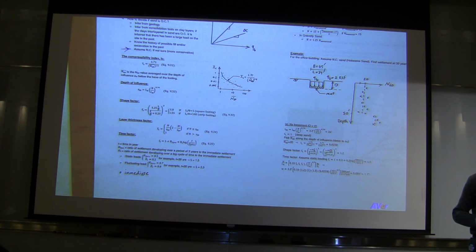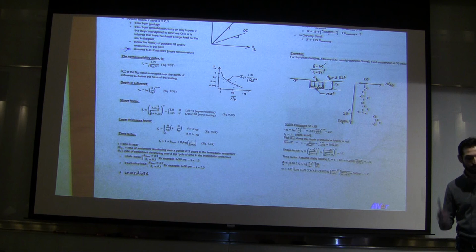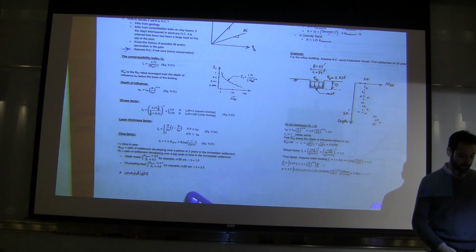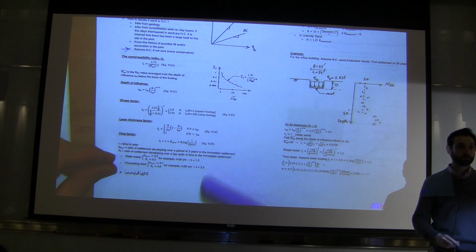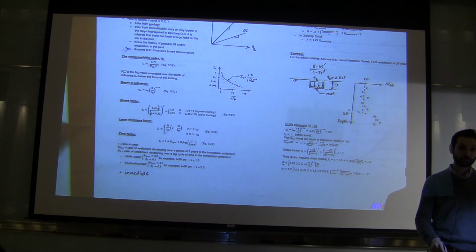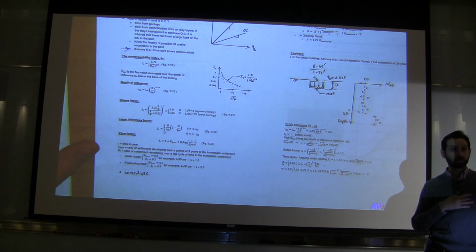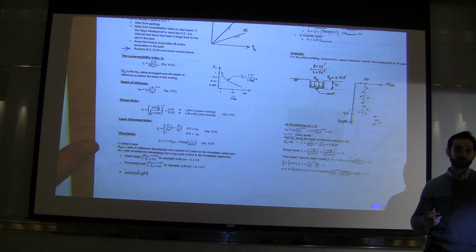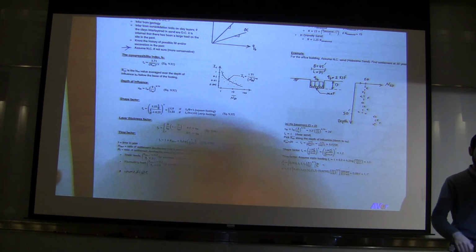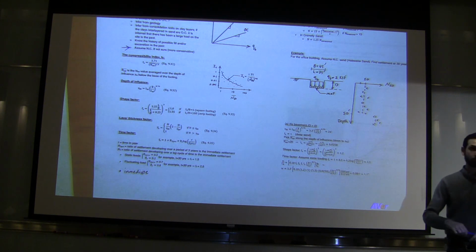I've never used this equation in practice, partly because I think this part of the equation is usually used for mechanical instrument foundations. For a lot of the dynamic loads that we deal with, like stuff that we design for earthquakes, anything seismic related, bridges, it's a whole different way of approaching it. So we don't really lump the dynamic component into these kinds of settlements.